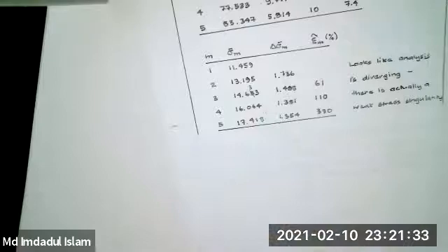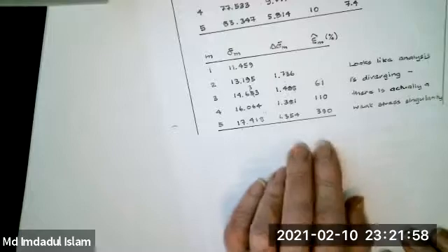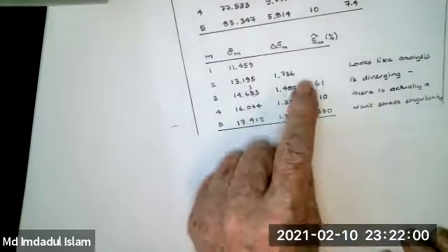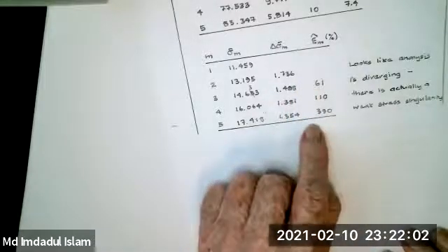And what's happening, and this happens at these stress singularities, is you have some regular stresses present, and they are converging, and they're going down. And the weak singularity is diverging. The stresses are going up, but they're not going up enough to mask or overcome the fact that you've got some converging stresses. And so the thing looks like it's converging. The error estimates I've given you, and this has been consistent for dozens of problems, will always be huge. And so it'll tell you, don't accept that stress.